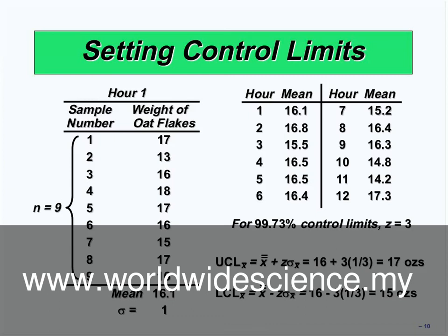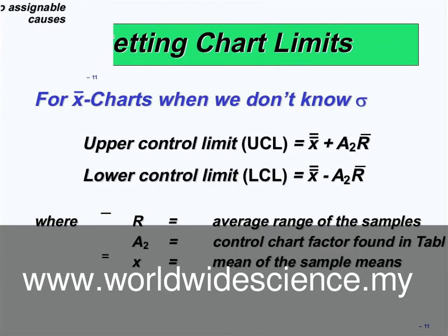Now you can use this standard table for A2. Okay, please don't look at the upper range and lower range. Only look at the mean factor, A2. A and this 2 have been given to you through this table. Sample size 2, 3. For example, sample size n in this example is 9, so A2 is 0.337.